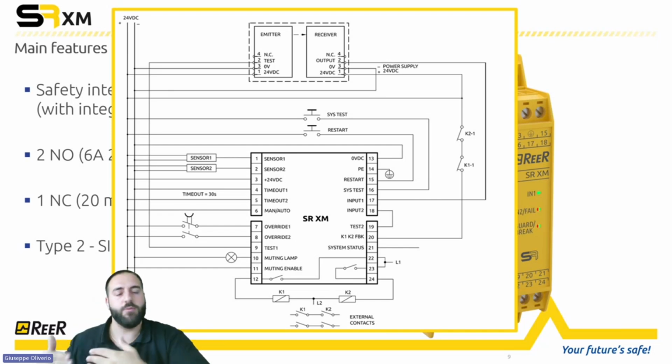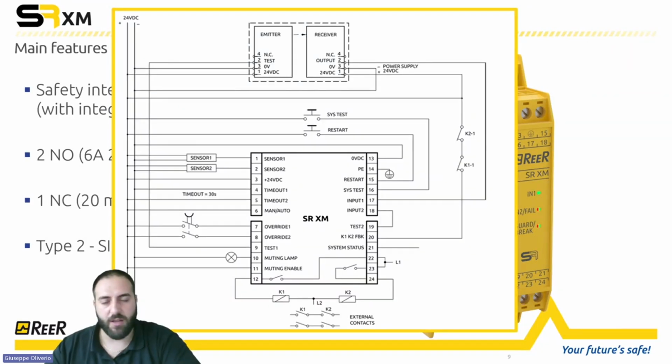So if you have a type 2 photocell, a type 2 application, a performance level C application, that's the right solution. Of course, if you don't need a safety controller, the reset input, the feedback contacts is always present also on that interface.